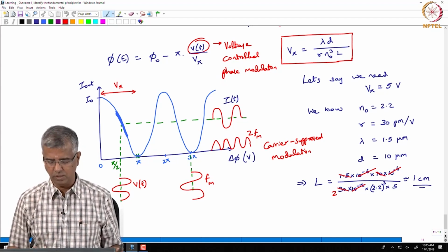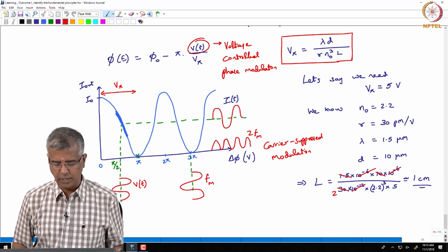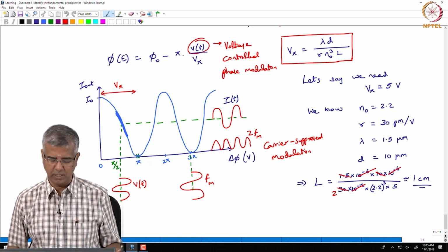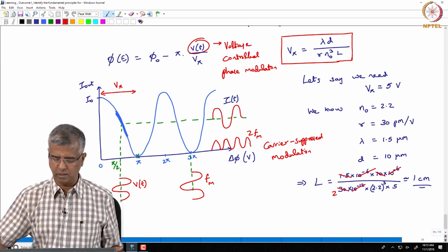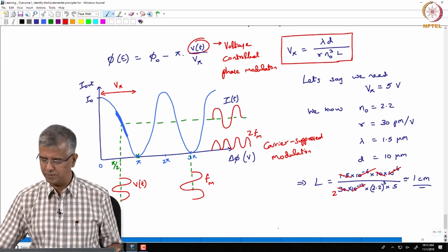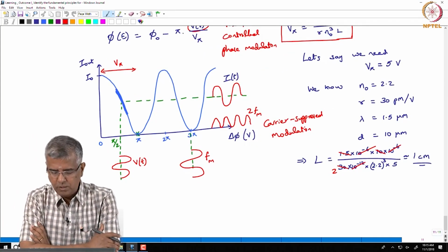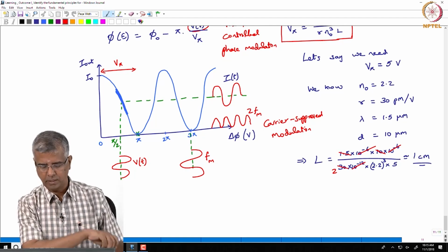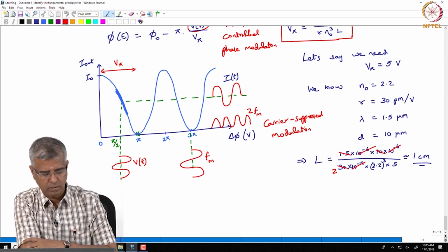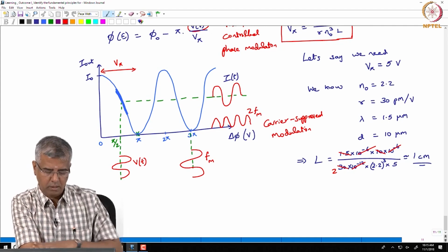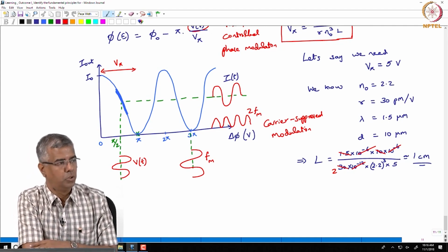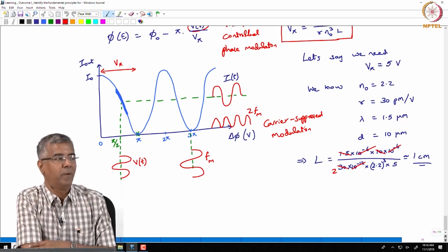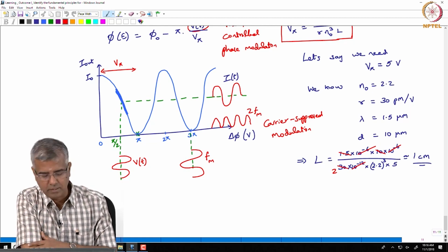So, you get a linear response, but there could be applications where you need to suppress the carrier and achieve modulation, in which case you can operate at the null point. So, the question is, does the frequency remain the same whenever you are modulating this electro-optic modulator using a particular voltage. So, yes, if it is linear, then you do not have any distortion. So, the exact replica of your modulating voltage would show up in the output. So, in that case the frequency is exactly the same.